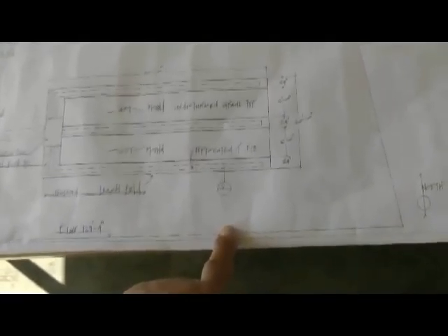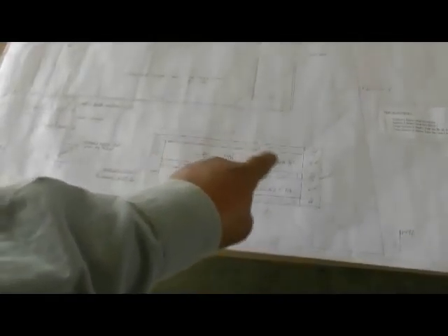This is scaled out in 3/16 inches equals a foot. So we'll probably be able to move this whole leach field more down towards the property line. If you notice the property lines, it's parabolic in the right corner. So if we were to take that leach field and move it down 5 feet from the property line setback, then I think we'll have more area where cars can park and the leach field can be built.